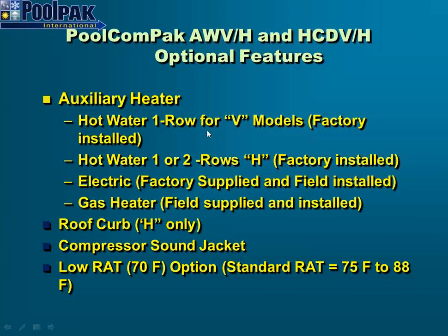Auxiliary heaters, you have a few choices here. You can heat using hot water, electric, or gas heaters. The hot water or electric is factory installed. Gas heater is field supplied and field installed. In this case, you would just use a fairly standard duct furnace. Highly recommend that you use stainless steel heat exchangers.